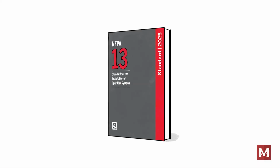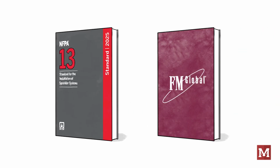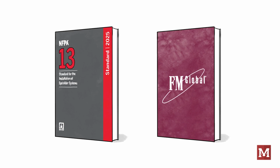NFPA 13, standard for the installation of fire sprinklers, is the standard we use for most projects in most places. Other standards are used for special clients, say FM Global, FM Datasheet 2-0, installation and guidelines for sprinkler systems. These are used for people who are working on projects for clients that are insured against fire by FM Global, which is an insurance company. This standard builds on NFPA's work, but generally requires a higher level of protection than NFPA 13.